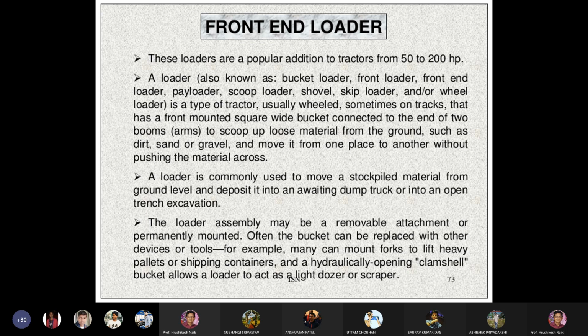In the case of shovel dumper technology, the shovel will load the material to the dumper. So if you are selecting a dumper of very big capacity, you have to select a shovel of equivalent capacity. Then only they will match each other. So you have to calculate the match factor between the shovel and dumper in the mathematical classes in the future.